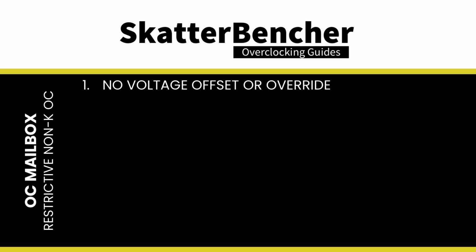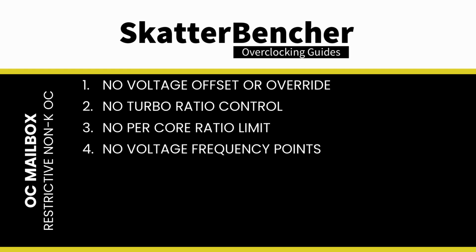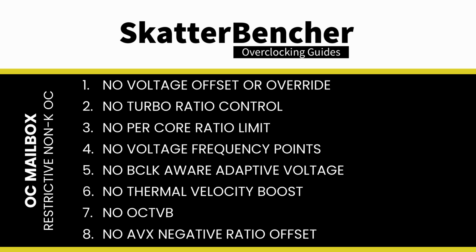This has a significant impact on the overclocking experience of non-K processors, as it means no voltage offset or override, no turbo ratio control beyond the default maximum limit, no per core ratio limit, no VF points, no BCLK aware adaptive voltage, no thermal velocity boost functions or OCTVB, and no AVX offsets.